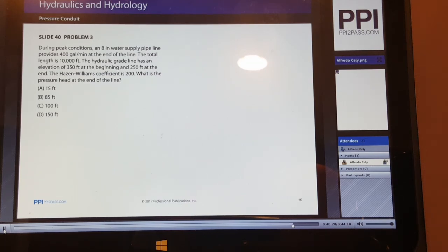You should be keen in identifying what energy components, is it pressure, velocity, or elevation, are acting at both ends of the water pipe. Then based on that, calculate the friction losses. And finally, you are ready to then solve Bernoulli's equation for the unknown value. Remember, that the change in the hydraulic grade line is the velocity head.